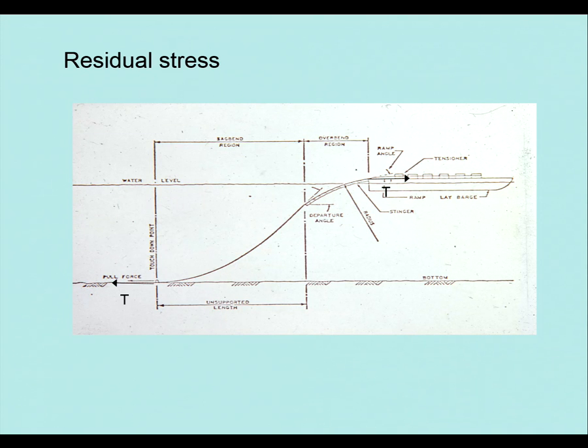So when you've got all these masses, if you want to start using them in formulas like bending moment formulas and that kind of stuff, you need to turn it into newtons. So you multiply it by g. Okay, so that's your displacement.